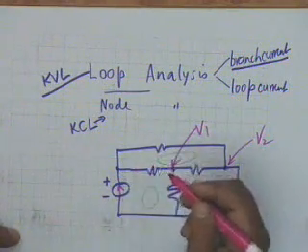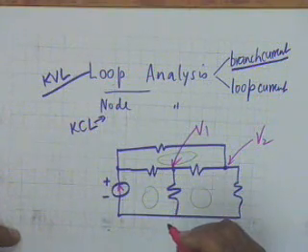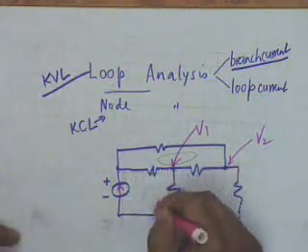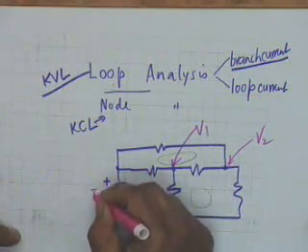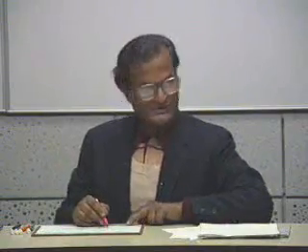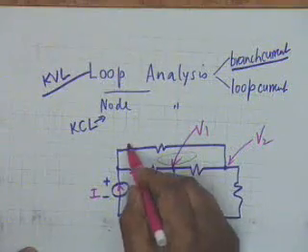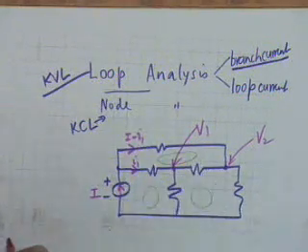So, all that you know is, now you cannot formulate loop equations. This loop equation cannot be written, and therefore, if this is a current source, now we are going to a different situation. If this is a current source I, then you formulate 2 branch currents, let us say I1, and this shall therefore be I minus I1.